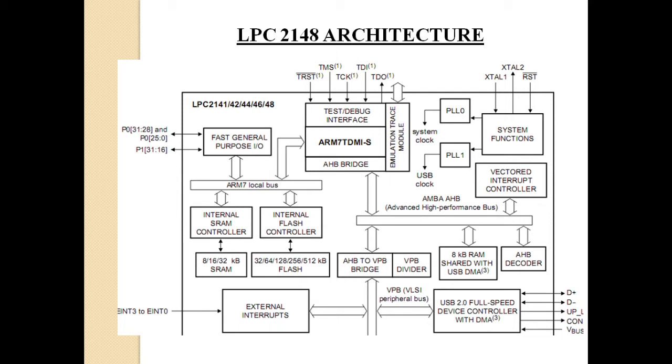How will you erase it? Using something known as ultraviolet rays. There will be a separate EPROM eraser for erasing EPROMs. So how will you apply the ultraviolet rays to the data stored in the IC? Ultraviolet rays are a light radiation. How will you take this light to the actual data present inside the chip? If you see an EPROM IC, in the center there will be a transparent window.